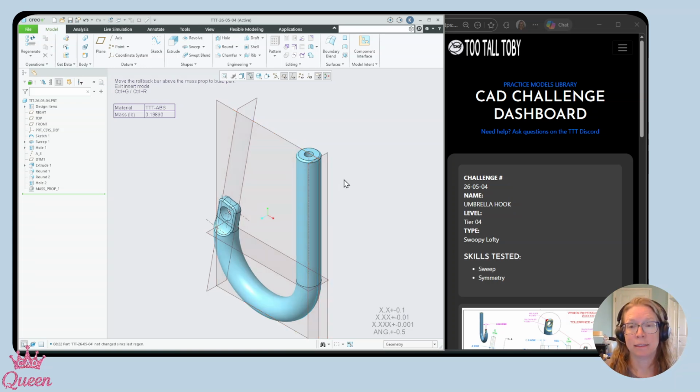Maybe not. When you're creating a coaxial hole outside of the steps I did here, you usually have to hold down Control to get the axis and then the start surface. I selected the start surface and then created the axis on the fly, so that kind of bypassed that need to hold down Control to get the second piece.